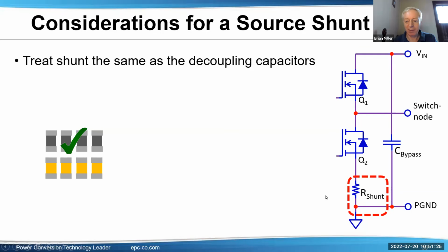If you have an amplifier, that's great, because you can look at the output of the amplifier and see a nice big signal related to the actual current. Or with an oscilloscope, if you have a good probe, put the ground right on the bottom of the resistor and the probe tip right on the top, and that should give a real good idea of the current going through there. I hope that's the question that was asked.